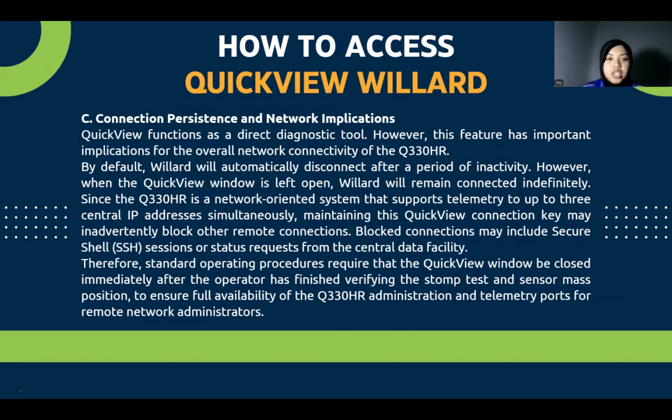C. Connection persistence and network implications. Quick view functions as a direct diagnostic tool. However, this feature has important implications for the overall network connectivity of the Q330HR. By default, Willard will automatically disconnect after a period of inactivity. However, when the quick view window is left open, Willard will remain connected indefinitely.